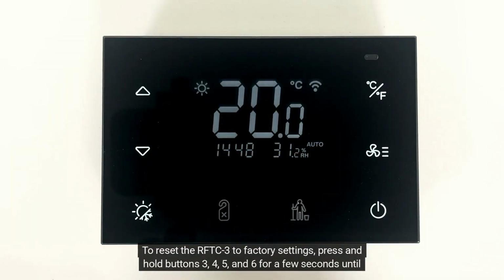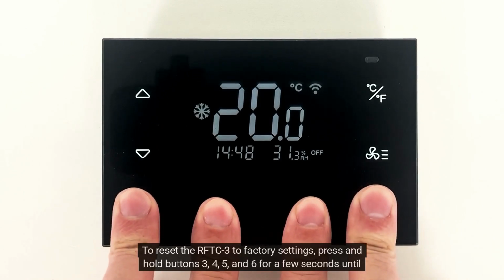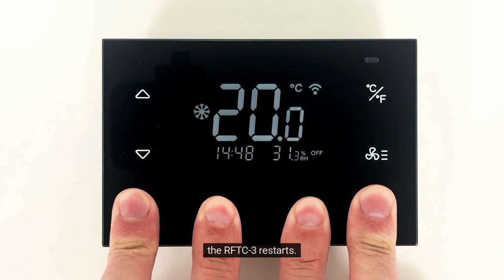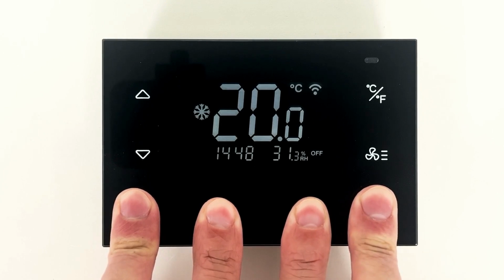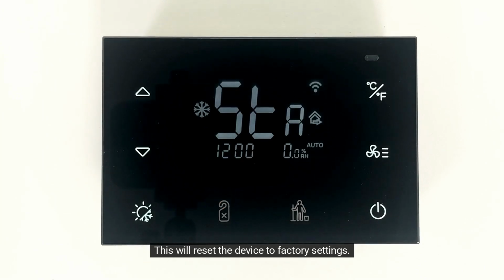To reset the RFTC-3 to factory settings, press and hold buttons 3, 4, 5, and 6 for a few seconds until the RFTC-3 restarts. This will reset the device to factory settings.